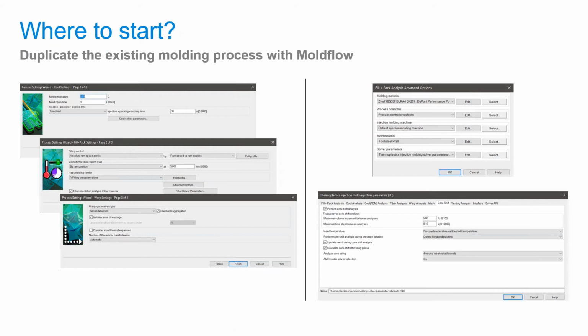With these settings entered to match your mold trial, you are now able to compare apples to apples when taking this original analysis and modifying it to find the resolution for the part quality issue that you originally stated. Once this simulation runs, the results should match very closely to those seen at the press. If not, then take another look through the study settings for any differences. And that would be through these process settings as well as the model itself, as something that seems minor could influence a huge difference in the long run.